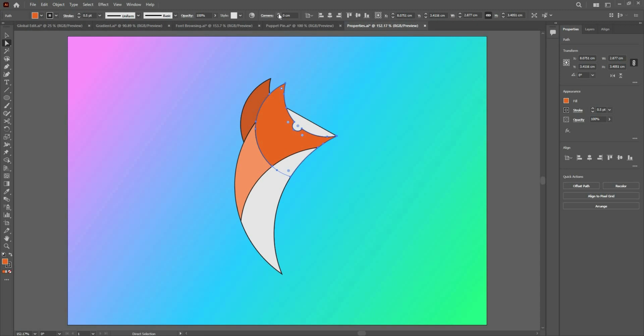That was not there before. It's nice and easy here. I can increase it by some physical increment, 0.1 centimeter, and make sure they meet. You can just type in the tweaks and press enter, and that'll do justice for us. Let's say about 2 centimeters. Hit tab, and there it gives me that. Stops at 0.2. It is not going beyond that. There's a limit to this.